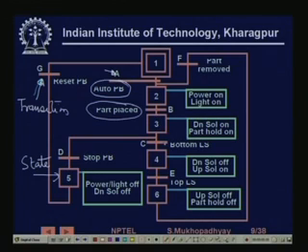Then from here it could go either this way or this way, depending on which one of these signals has come. If the stop push button has not been pressed, then eventually the bottom limit switch signal will come and it will go to state 4, in which it will activate these outputs.